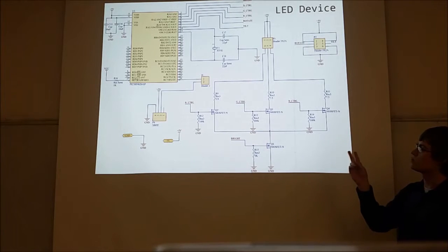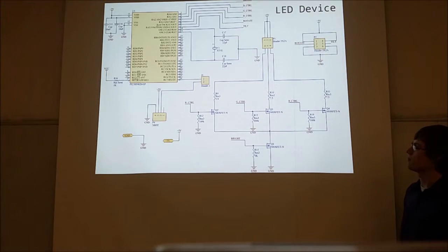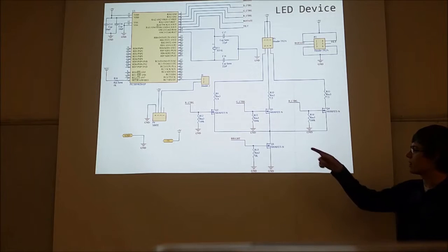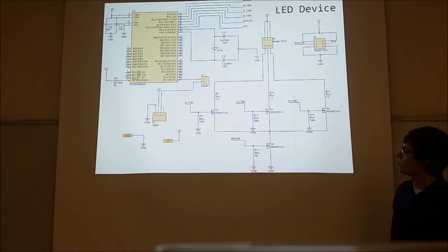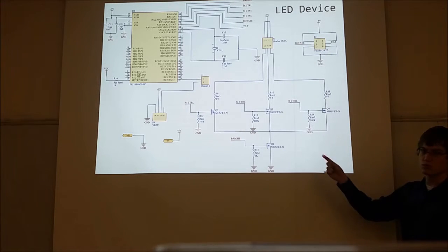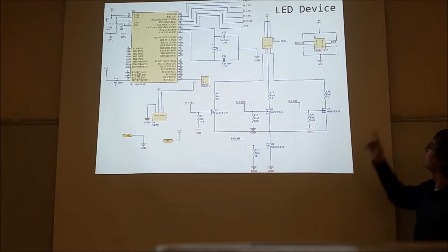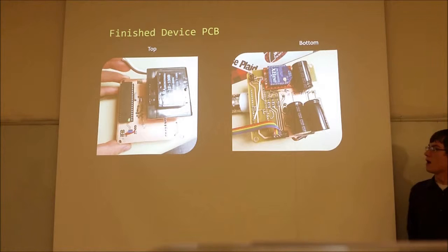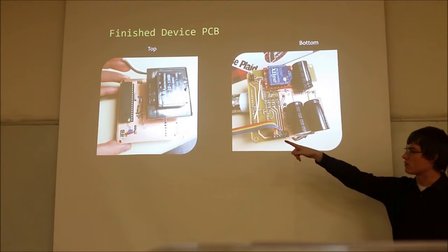The PIC's over there with 2 caps decoupling the power lines. We have the Zigbee talking to the PIC through RC7 pin there. And then we've got 4 FETs that control each color individually and the brightness through pulse width modulation. And we have 2 headers that come in to control the rotate and the tilt motors, which are all through pins RA0 through RA5.